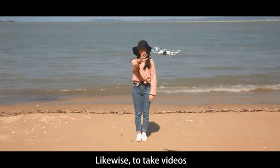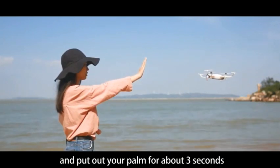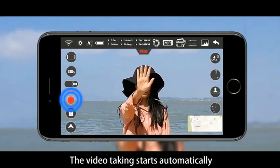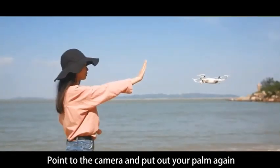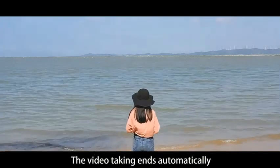Likewise, to take videos, face the front camera at a distance of 1.5 meters and put out your palm for about 3 seconds. When the aircraft indicator keeps double flashing, the video taking starts automatically. Point to the camera and put out your palm again. When the aircraft indicator stops double flashing, the video taking ends automatically.